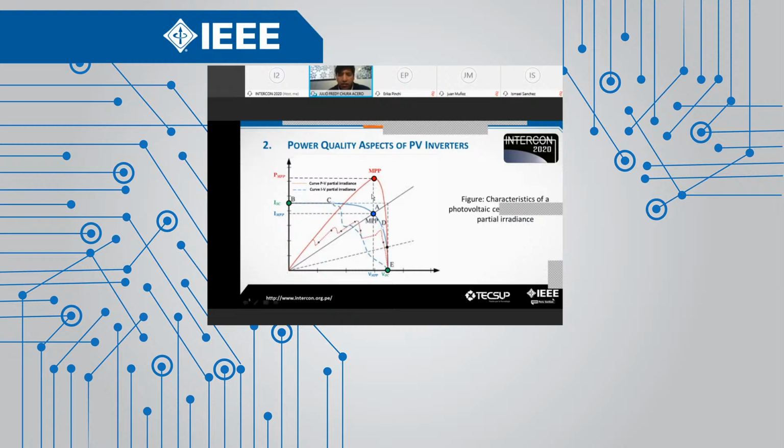In this figure, we can see how the MPPT is working. We can see the maximum power point and the voltage, how the voltage works with the current, the short-circuit current. The red line is represented by the PV curve, partial irradiance, and the blue line is represented by the IV curve, partial irradiance.